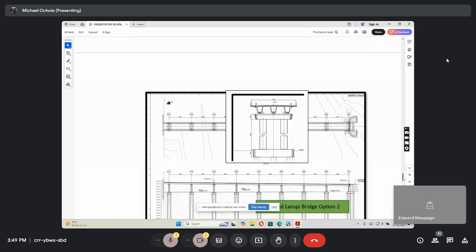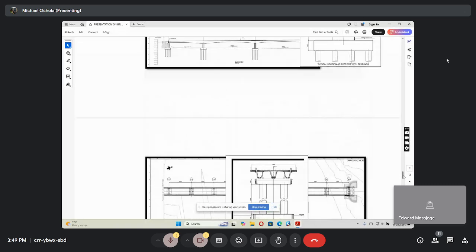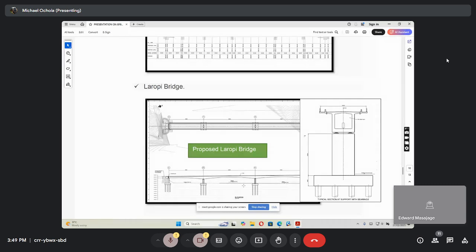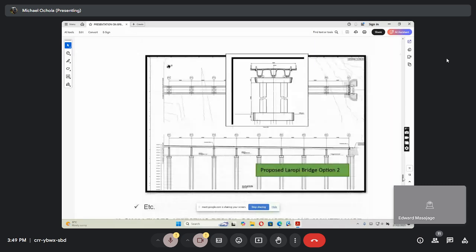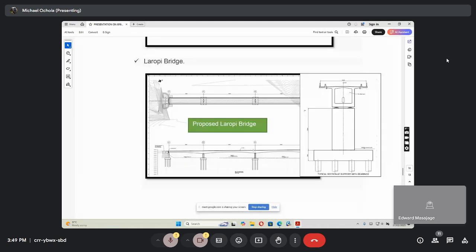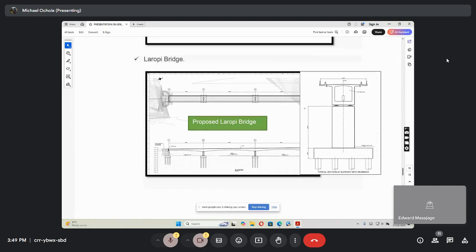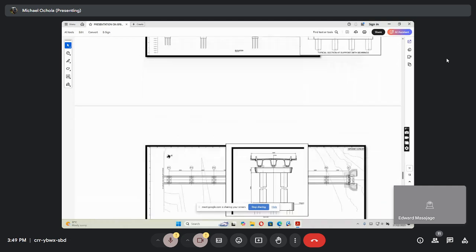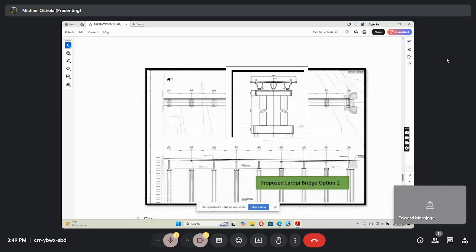But the question is, which my student or your student will have to do, is here. You look at this. This is basically about 900 meters apart, and there are few foundations. But down there are 40 meters and many. So you may find that the foundation costs tend to be higher than this one. But that is left at the design stage. For now, you're only understanding that they're there, but you must verify constructability, costs, functionality to give you a higher value for one choice to be taken.